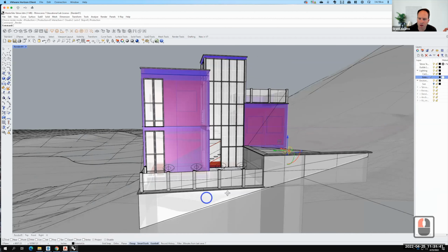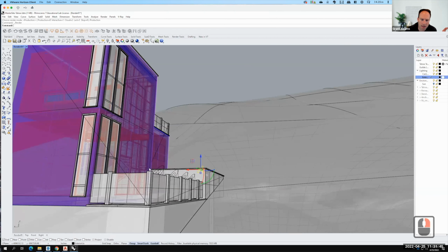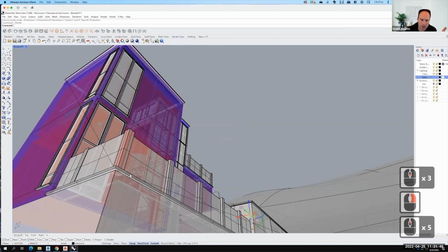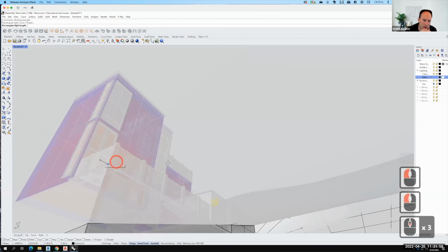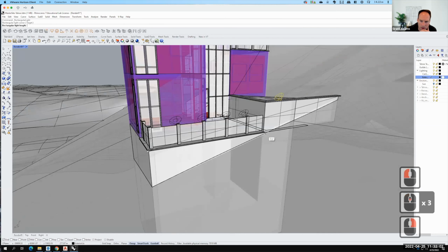Now, maybe you want to do lighting in a different way. Maybe you don't want spots going up. You could do a rectangular light that washes down a particular surface. So I'm going to do it right along this edge, this little overhang. So let's go ahead and create a rectangular light. Remember, the challenge with rectangular lights is figuring out what the intensity should be. So let's come along here to that end.